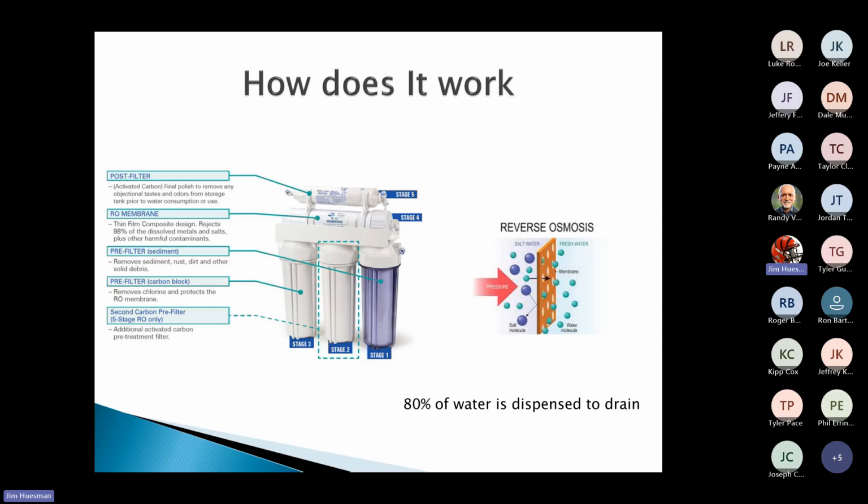If we would run that in any sort of metallic piping, copper, galvanized, anything that's out there, if you would run that through a copper, you've got about 30 days because water is so pure that as it's running through that copper tubing, it is actually starting to strip the materials out of that copper because water is going to take back what it wants. And it's going to start stripping a lot. So if you do run RO water and on the downstream side, you're using copper, be ready to change it. You've got yourself about 30 days. Okay, it'll eat it all out.